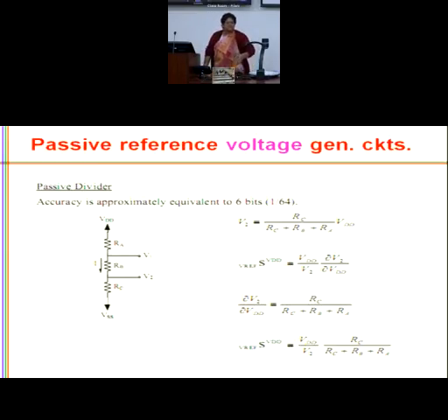If VDD directly is coming over there, compute this value, it will come out to be 1. It's a very bad design. So I should not use a resistor ladder to generate a VREF. Got it? This is coming out to be 1 because of VDD by V2. What is VDD by V2? It would be RC plus RB plus RA by RC. Substitute it here, everything will cancel out. It will come out to be 1.